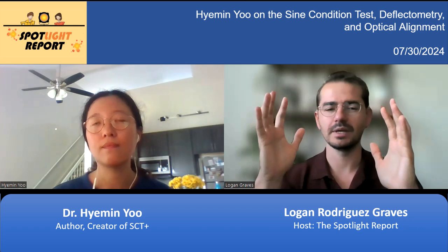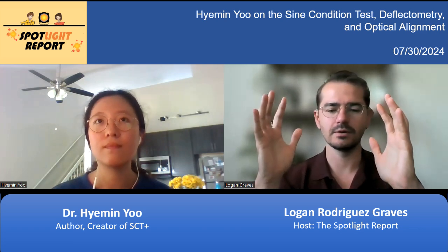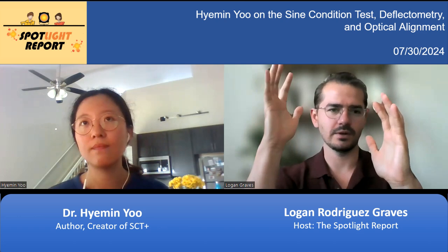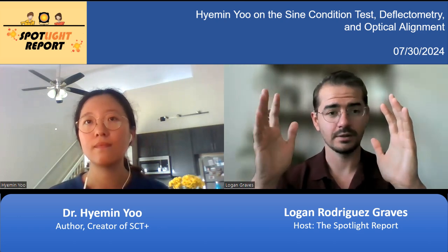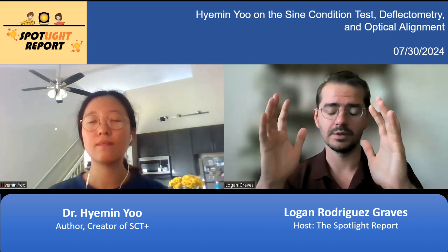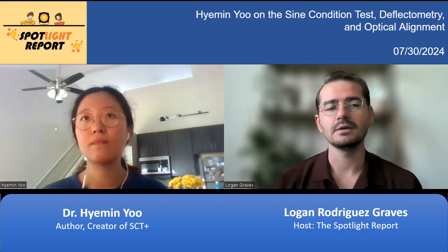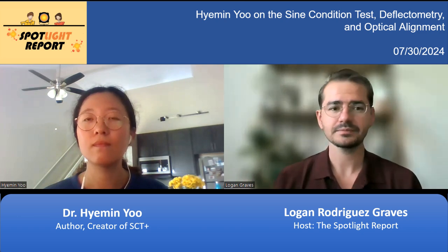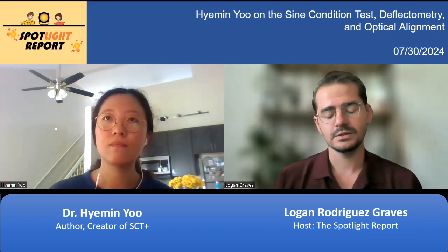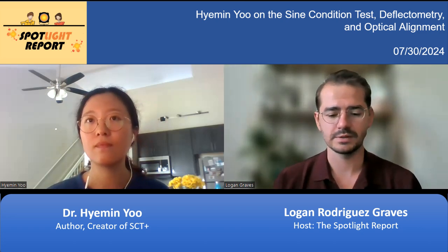You have your design, so you can make your misalignment matrix, and you know if I shift lens two relative to lens one in decenter or spacing or possibly clocking, and this will be relevant in a second, I'll get some unique systematic misalignment mode of these five modes that you're discussing, and you can analyze it in some way. And so you transition to talking about the Abbe sine condition, which was, I think, from Ernst Abbe.